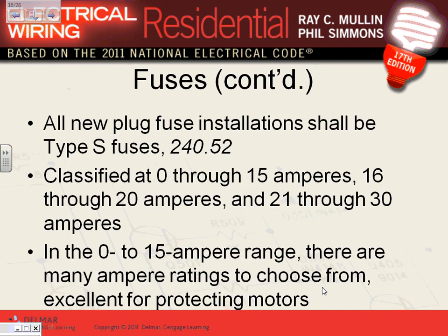Plug-in fuses. I don't know how many of you guys, probably, Chris, you have done it many times. What happened in the fuse boxes in the past is if the fuse blows and you don't have this size of fuse, you use a penny, you stick the penny under, and you screw the fuse over it. So you basically defeated the purpose of a fuse, right? Or what happened in the past, we used a 15 amp fuse, and you don't have a 15 amp, you have a 20 amp fuse, and they fit. So you put a 20 amp fuse. So now you are having a number 14 conductor carrying, say, 20 amp or 24 amps or so. So you're basically overloading your conductors.